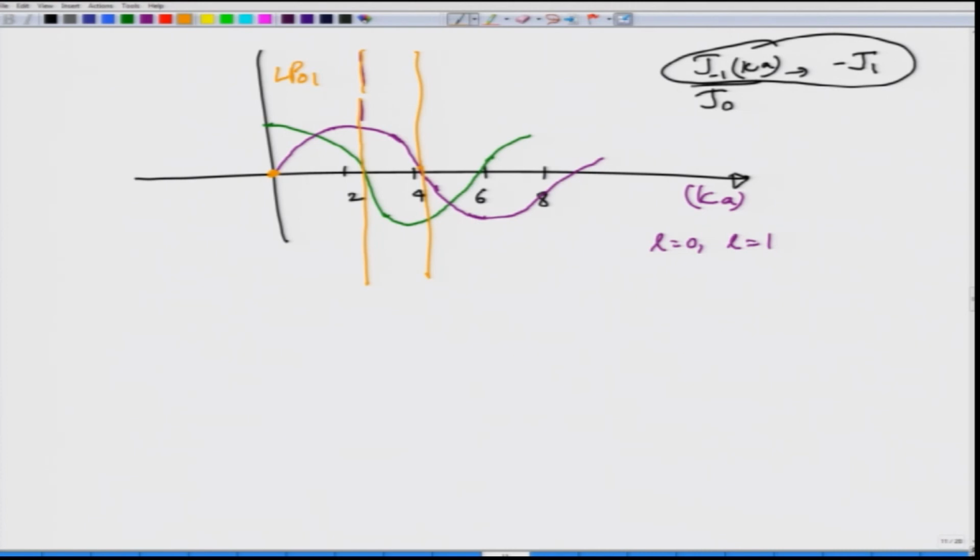Okay. So, in the next set you will have the LP11 mode, but from our previous discussion you also know that in this range you actually have the true solutions, which are TE01, TM01 and HE21 as well. So, what you can actually see is that LP11 is a linear combination of 3 modes: TE01, TM01 and HE21. By combining these 3 modes appropriately you can obtain different LP modes. Of course, the next time the Bessel function J1 goes through 0, you will have LP02.